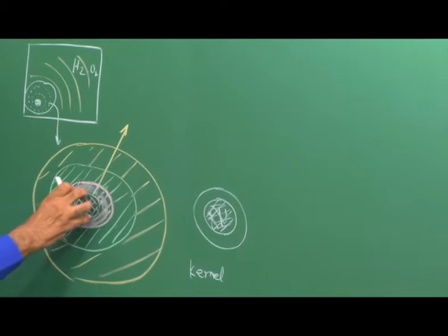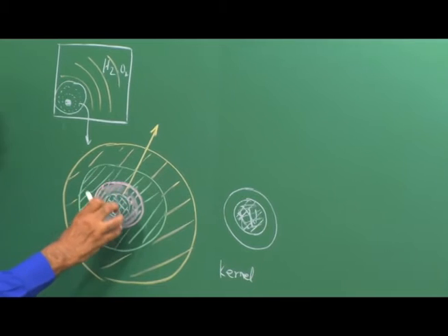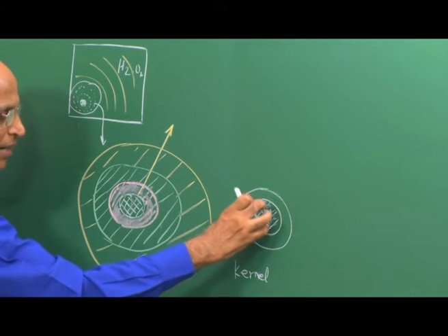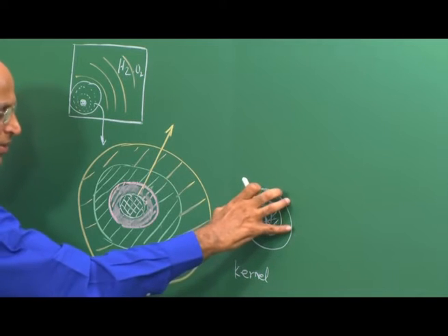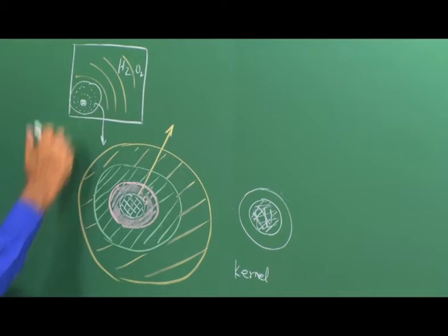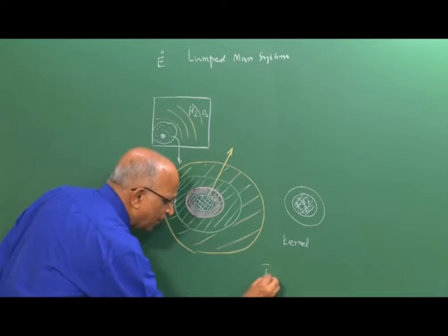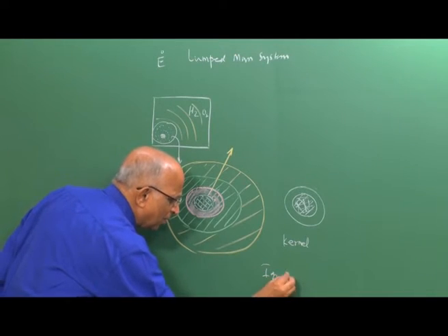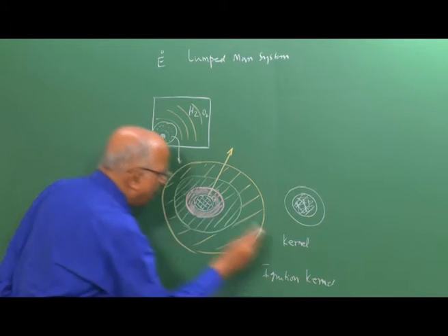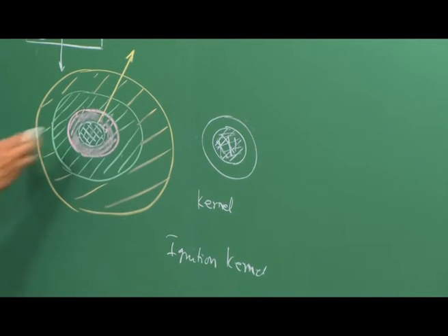If I do not have an adequate kernel for ignition, the ignition kernel will collapse and it will not be possible for it to heat the adjacent layers. Therefore, from an ignition point of view, it is necessary to make sure that the size of the ignition kernel should exceed some threshold value, and this is what I want to do.